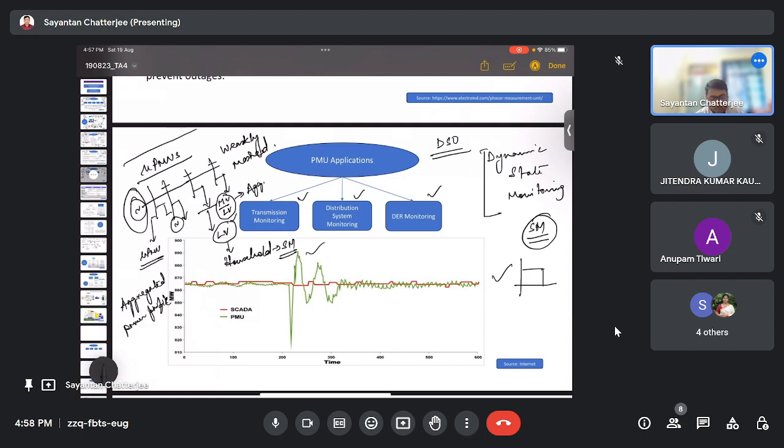then people choose the DSOs, or rather, let's not consider DSO, because the objective of this DSO planning and all these things was only recently proposed, some 2 to 3 months ago. So that can't be the case in the Indian context, but outside India, this smart grid architecture based on distribution system side monitoring can be considered. The smart meters would be delivering aggregated data, and for the nodes where we don't have data, we generally make use of pseudo measurements.